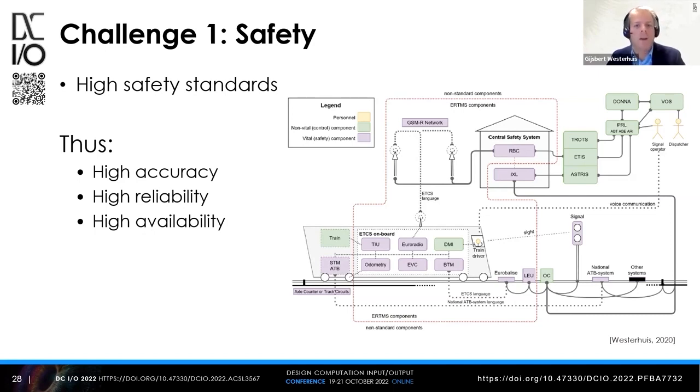So this is why the timetable is set up by people at the infrastructure manager, and then we test it again using simulation, but then again check the clashes that come out as a result of the simulation by hand, and check every clash and write on that in a report. And that's for safety purposes.